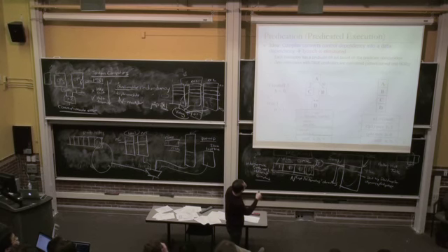So basic block B and basic block C have instructions, and instructions take predicate registers, meaning another register source. In this case, this instruction is supposed to execute if predicate 1 is false, and this instruction is supposed to execute if predicate 1 is true.